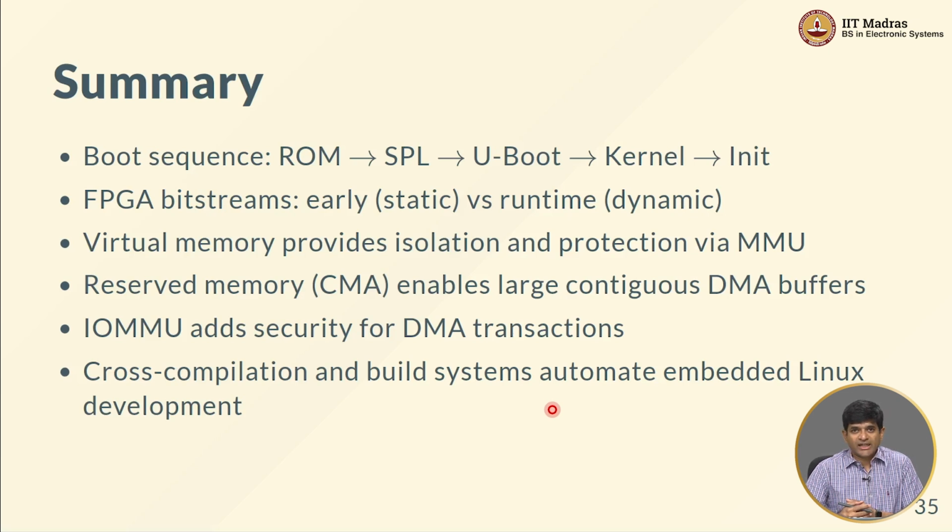Alright, so to summarize everything that we have talked about so far, we started off with a discussion about boot sequences, the process by which we go through ROM, multiple different bootloaders, U-Boot, eventually the kernel and user space, right. We also discussed where we might want to introduce the FPGA bitstream into the system, either very early in boot.bin or in U-Boot, or perhaps at runtime.